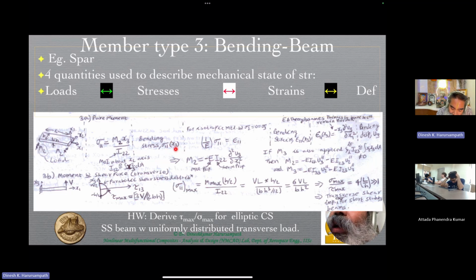So in other words, for very large positive values of x3, you will have one direction, and for very large negative values of x3, you will have another direction. So that's essentially what's happening. Coming back to the same example of the aircraft, because of the lift distribution, you have the top portion under compression. So your sigma 11 that you see over here will be negative at x3 values which are positive, if you've introduced a coordinate system such that x3 is upward positive. At any location over there, you would see that it's under compression, and therefore your sigma 11 value will be negative.